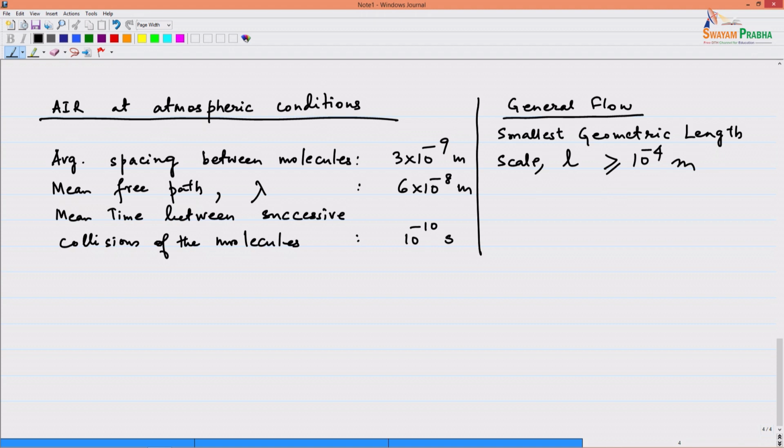So we use the Knudsen number for the separation of length scales. Length scales become very important in understanding turbulent flow, because you will see slowly that there is behavior in turbulent flow which is not very dominant when the length scale is of a certain size. That sort of behavior is happening only at a very small length scale.